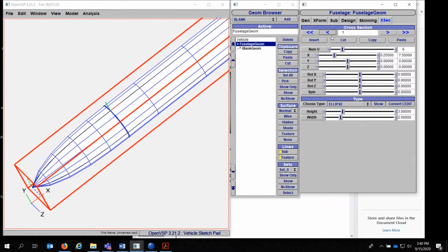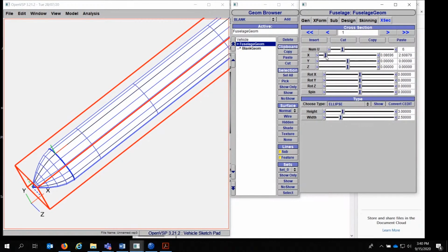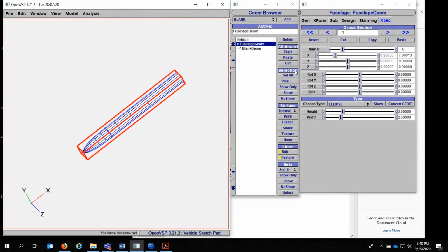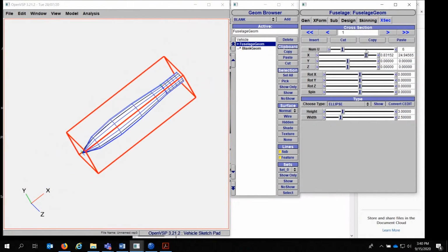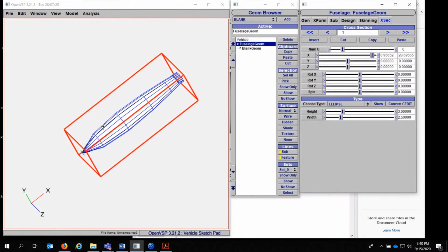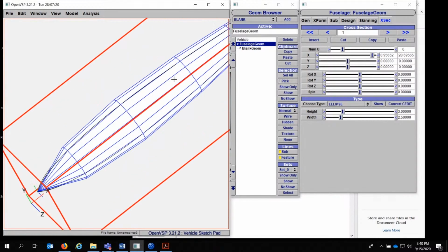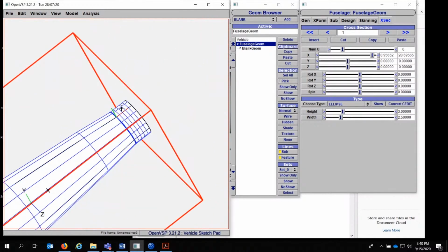And it doesn't matter where I move this cross section, that is U equals 0.5. It doesn't matter if that cross section is right next to the leading edge or if I move it all the way back to the trailing edge, that's where U equals 0.5. So U is 0. It's probably a quarter-ish around here. It's 0.5 right here, and it's 3/4, somewhere right there. So it's not linearly spaced, which can be frustrating if you were expecting that. But if you know that's a feature, you can use it really to your advantage on how to do this.